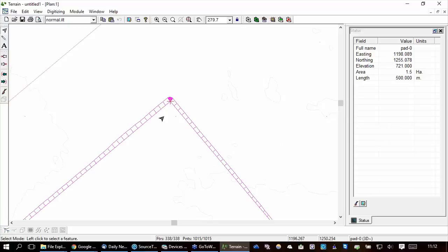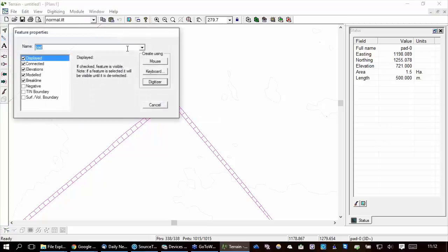So it created all these little legs to get from the surface down to ground, and let's create a new feature called section. I want to see the elevation of the design surface in the foreground as well as the background surface, and that's automatically done if I create a draped feature. So a draped feature looks like this. It's modeled so it looks at the surface, but it has no intrinsic elevation. It actually drapes the feature on top of the two surfaces.